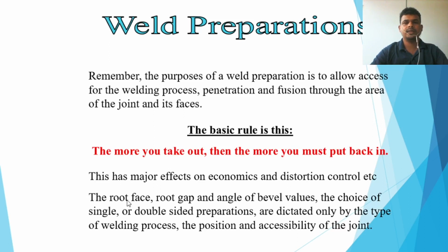The root face, root gap and angle of bevel, the choice of single or double side preparation are dictated only by the type of welding process, the position and accessibility of the joint. So at the weld preparation time you need to consider this.